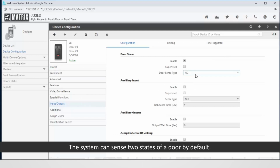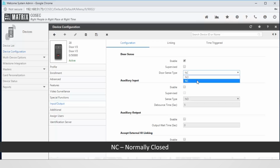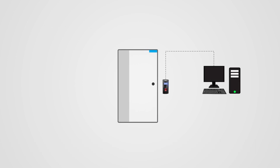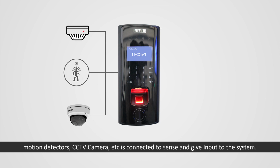The system can sense 2 states of a door by default: NO, normally open, NC, normally closed. Any change in its normal state will lead to trigger the system for output. Auxiliary input can be configured when an input device such as smoke detectors, motion detectors, CCTV camera, etc. is connected to sense and give input to the system.